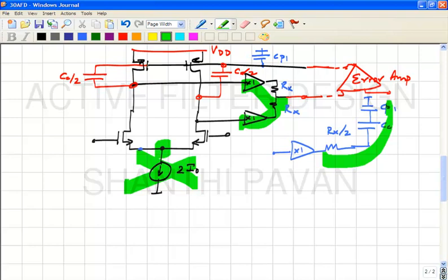You can take two common source amplifiers and operate them as two individual units and simply look at the difference between their drain currents, correct? So that circuit will have the same equivalent for both differential and common mode signals. We have seen all this during EC201, correct? So what is the advantage of having the tail current source?